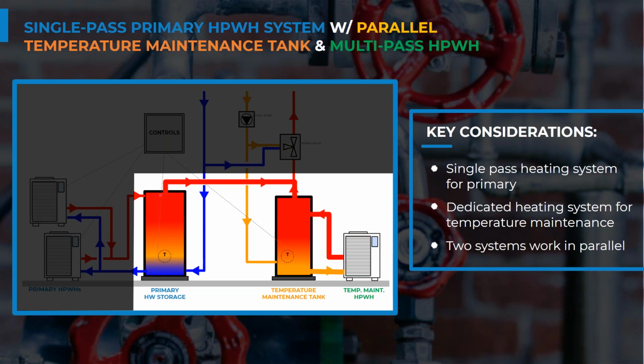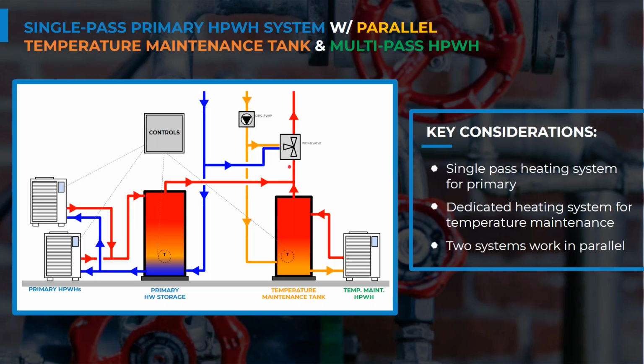I will note that this pipe is uncirculated because the circulation isn't going back to it. So during periods of low use or no use, like overnight, this water in this piping can cool down. And if that happens, then we might get a little bit of cold water on the hot side of our mixing valve.